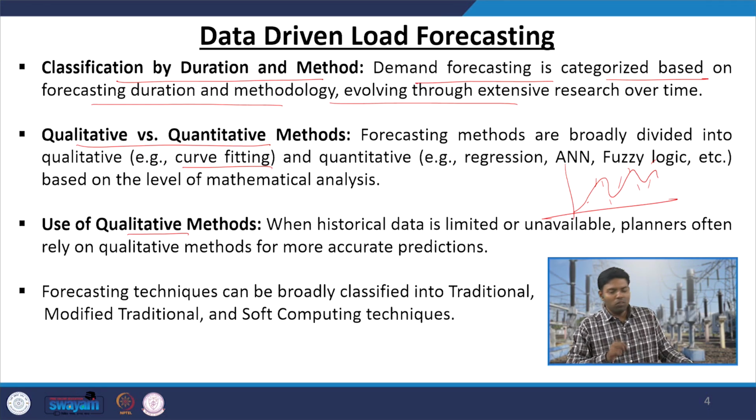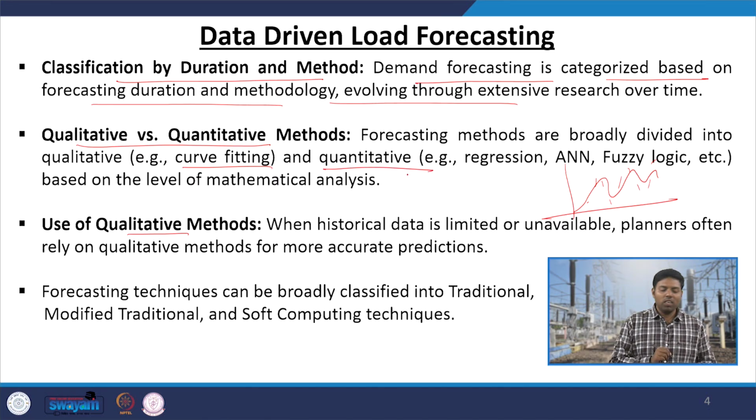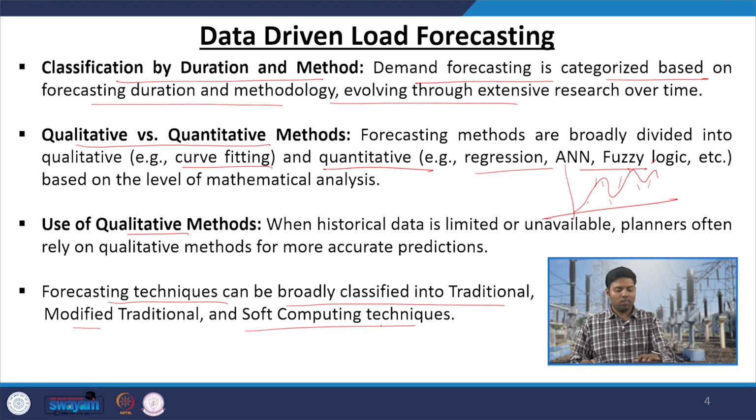But if you have a huge size of data set, then we go for quantitative load forecasting, and that is done by regression, ANN and fuzzy logic and other kinds of deep learning technologies. Depending upon that, your forecasting techniques can be broadly classified into traditional, modified traditional and soft computing techniques.